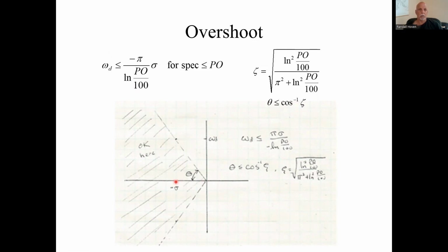So if you give me a sigma, pick any convenient sigma, ratio it up by this formula, and that gives me a point on the line. Now I just draw a straight line, and it's symmetric. Here's that other relationship with damping ratio that I never use. I use this formula, or this formula. You kind of forget about this. I just find it too complicated.